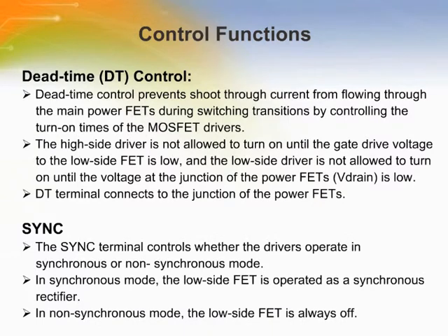This slide offers information about control function of TPS2831 device. Dead time control prevents shoot-through current from flowing through the main power field effect transistor during switching transitions by controlling the turn-on times of the MOSFET driver. The sync terminal controls whether the drivers operate in synchronous or non-synchronous mode.